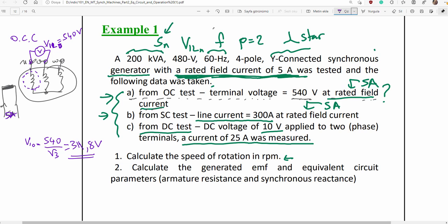That is the voltage induced across one phase coil. Remember, here is the EF, here are some impedance elements, and then here is terminal voltage of one phase. In case there is no load, in case there is no current, terminal voltage under no load condition is equal to induced EMF, field EMF in the machine.